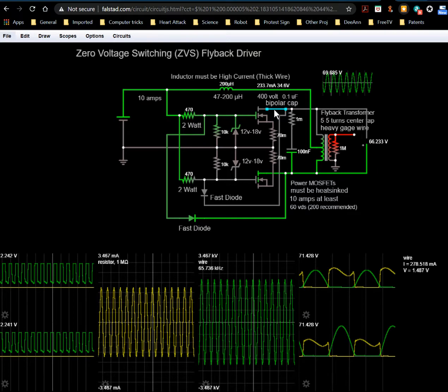That's the key thing to remember, that there's a voltage on this capacitor, and this transition actually happens when this voltage across here that I'm measuring, this voltage across this LC circuit, gets to the point where it's crossing zero, right across the middle here. That's when this transition occurs. And there's a reason for that I'm going to get to in a second.